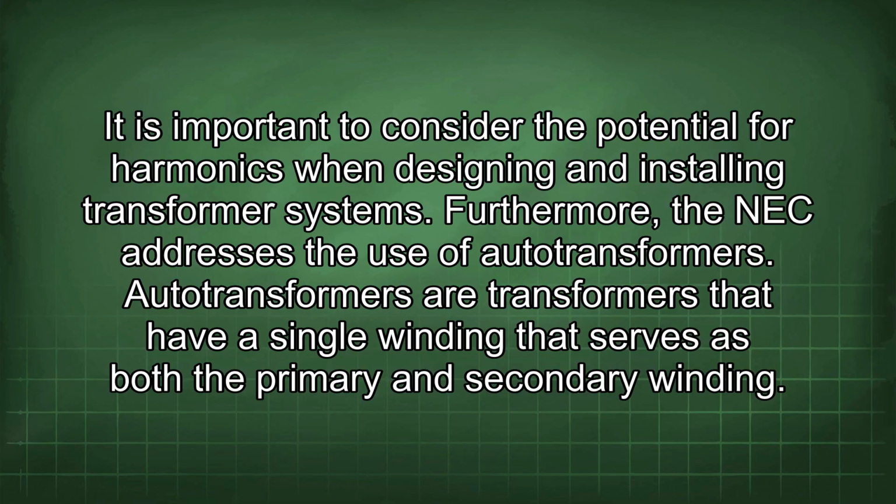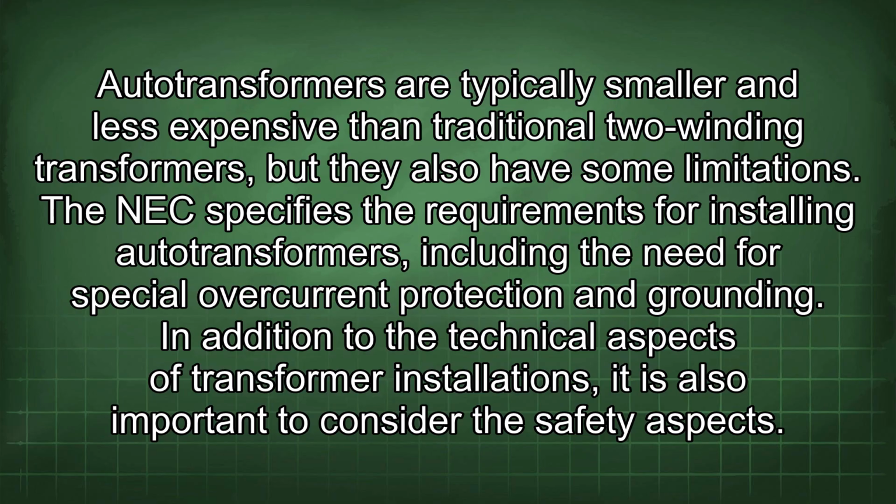Autotransformers are transformers that have a single winding that serves as both the primary and secondary winding. Autotransformers are typically smaller and less expensive than traditional two-winding transformers, but they also have some limitations. The NEC specifies the requirements for installing autotransformers, including the need for special overcurrent protection and grounding.